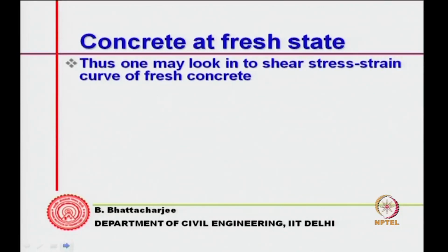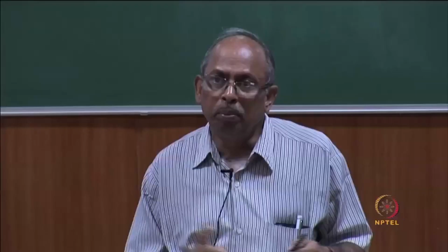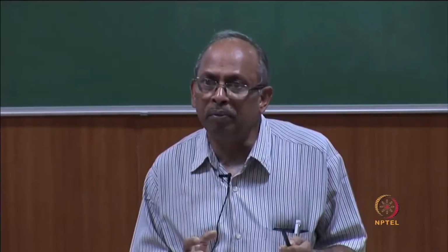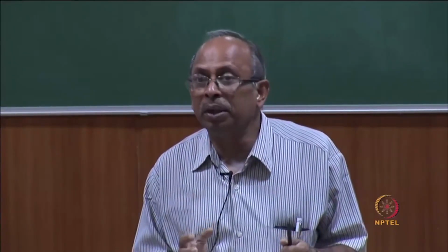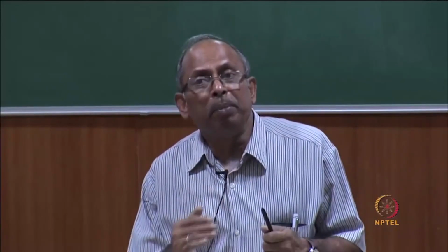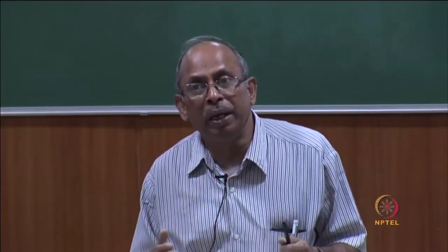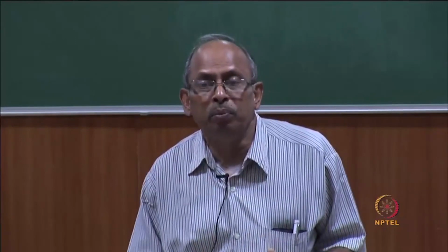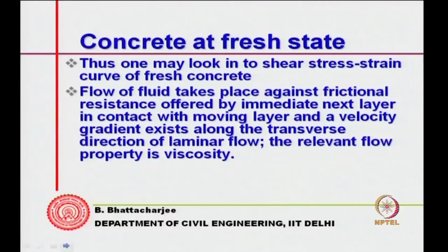So, we must look into the shear stress strain behavior of fresh concrete, because while compacting we apply some kind of vibration, and under the vibration it is subjected to a kind of shear stress. At a given particular shear stress it will start moving, and then the flowing would start. So, you can look into this behavior of fresh concrete. Now, if you look at it, it has to have flow.